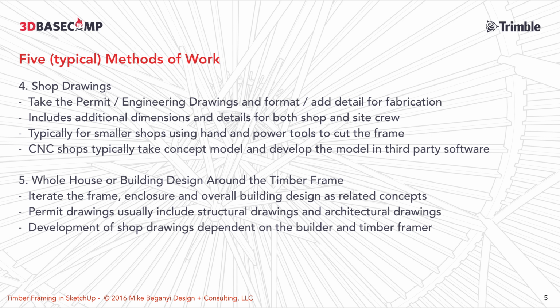Shop drawings are a lot more involved, I think, depending on what you're doing with the project. So we take the permit engineering drawings and we format and add detail for fabrication. We include additional dimensions and detail. Sometimes you have a really inexperienced crew, so you've got to show them what all the joints look like.